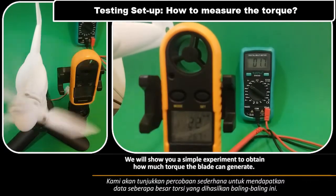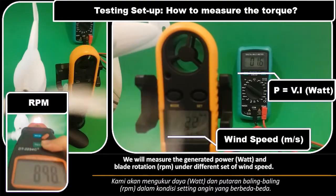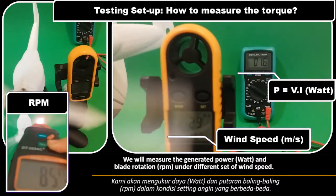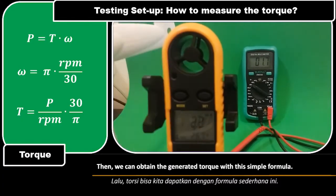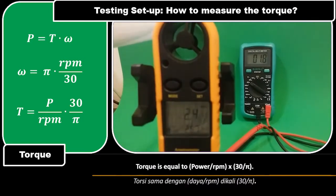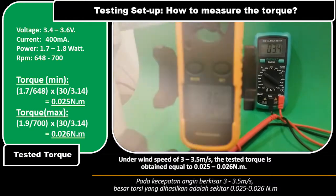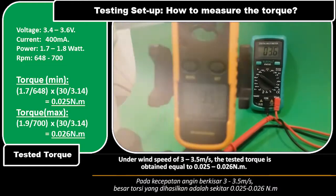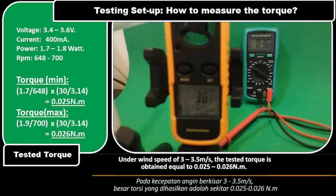We will show you a simple experiment to obtain how much torque the blade can generate. We will measure the generated power in watt and blade rotation in RPM under different set of wind speed. Then, we can obtain the generated torque with the simple formula. Torque is equal to power divided by RPM times 30 over pi. Under wind speed of 3 to 3.5 meters per second, the tested torque is obtained equal to 0.025 to 0.026